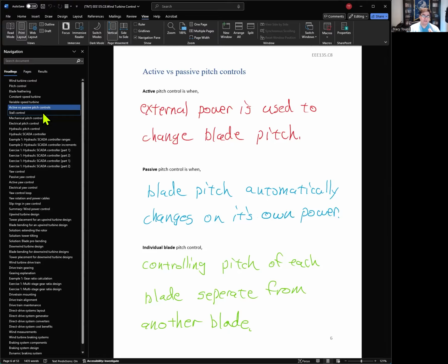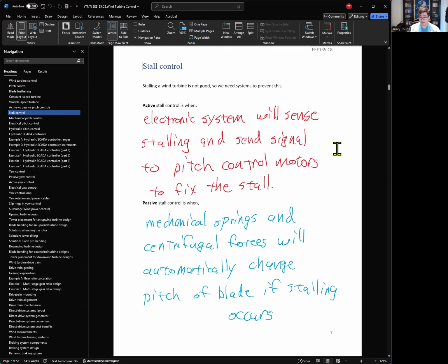Okay. So other things for wind turbine control is we need stall protection or stall control. So if you remember, stalling is when you put that blade pitch too much and you go past that critical angle of attack where now there's too much drag, not enough lift, so you're kind of losing power. You went too deep on the angle, okay? So we need to make sure it's like skirting the edge of disaster, because the critical angle of attack is right before when we start stalling. So we want to get all right to that point and then stop. If we get too far, we start stalling.